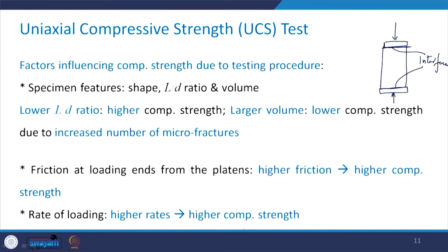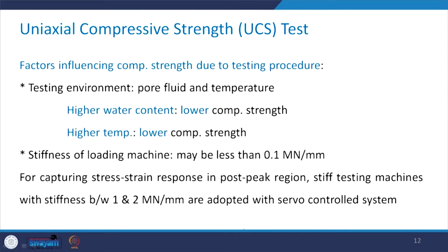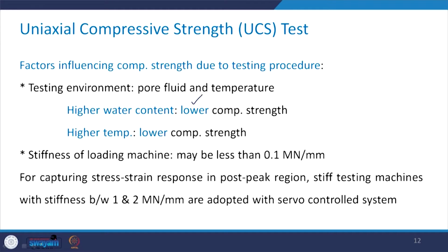Rate of loading: if we apply the load at a higher rate, you will get a higher compressive strength. Then the testing environment, which includes pore fluid and temperature. In case the sample or specimen has a higher water content, it has lower compressive strength, and if you test it at a higher temperature, you will get lower compressive strength.